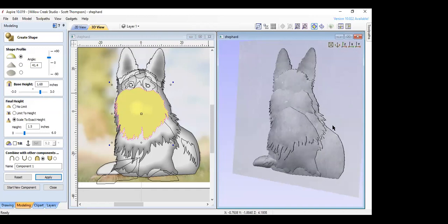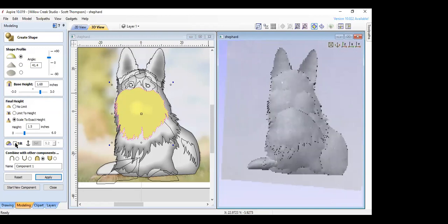And I want those cheeks to show up on both sides of that face like that. So I'm going to use the same tilt function again. I'm going to click tilt. And once it's ready, it says it's ready, I'm going to hit set. It's set, and I'm going to set the hinge point right here.